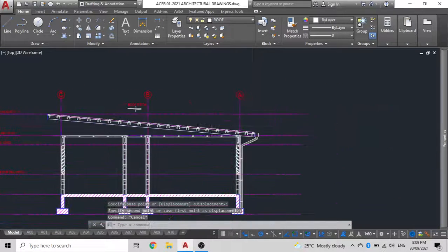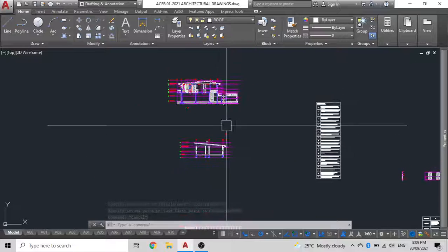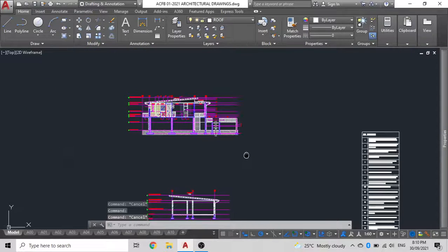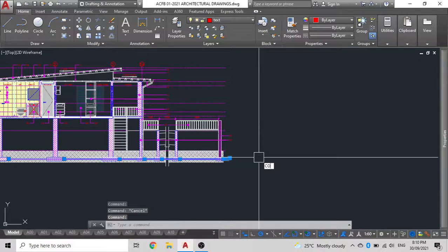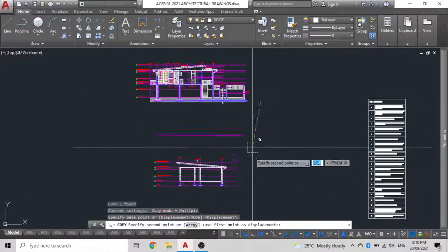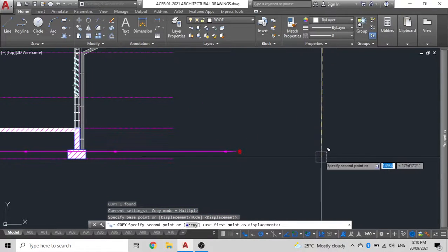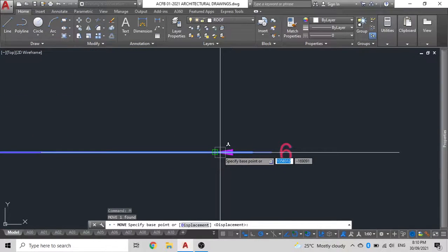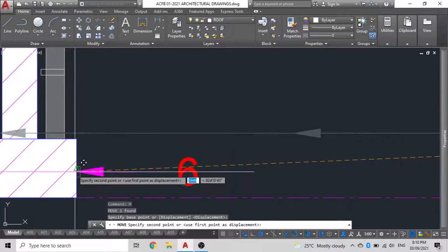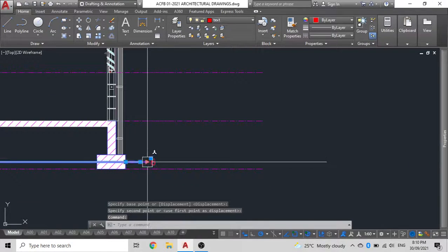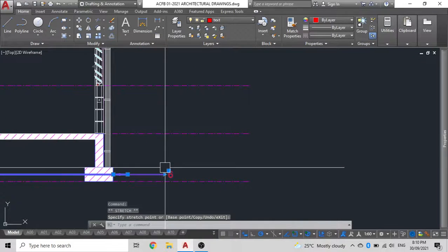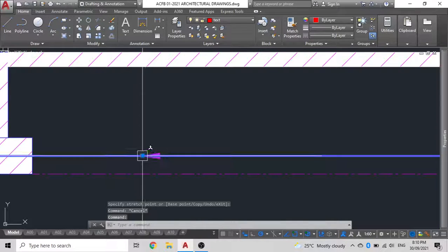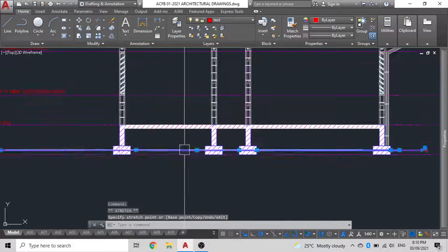Now that that is done, we can start adding our annotations. Now I'll just basically bring down one of the annotations from one place, and then I'll use that as my example. So I'll copy this number 6 down and just paste it accordingly. Then I'll move these guys into place and paste them there like so. Ensure that my numbers are slightly overhanging this line so that I have enough gap to put my multi-leaders on the fascia board in other places.